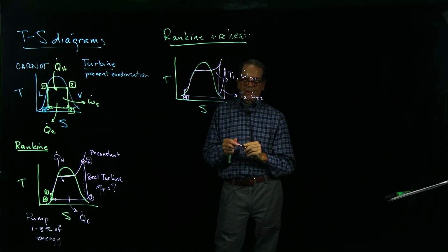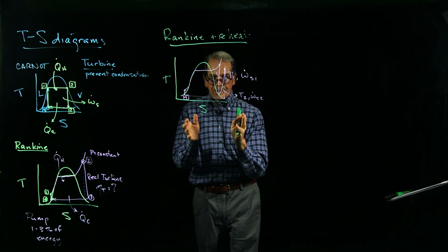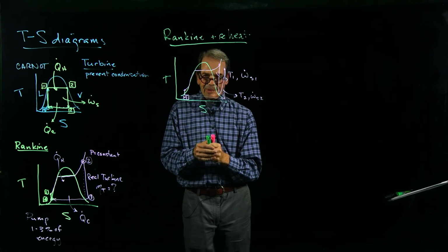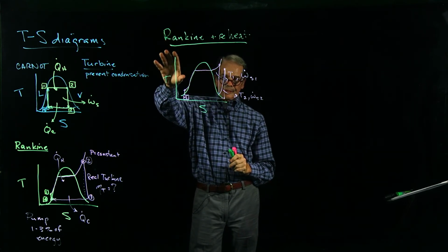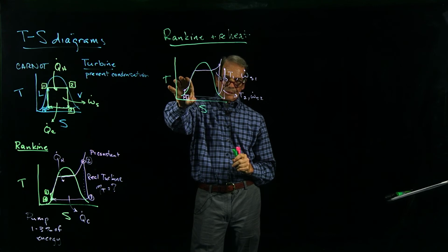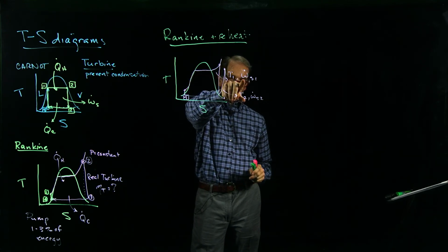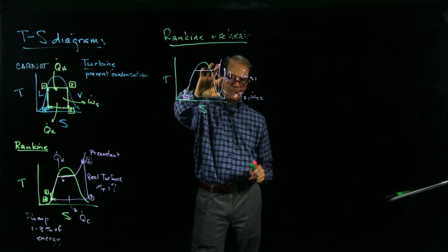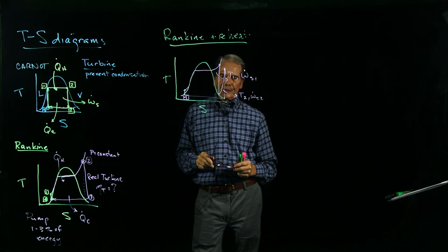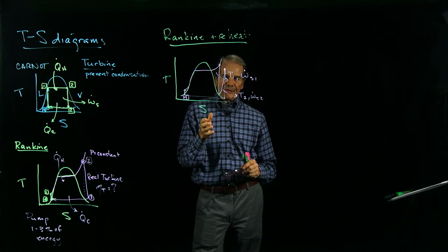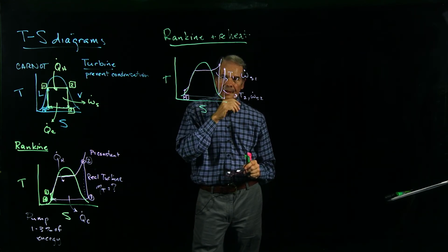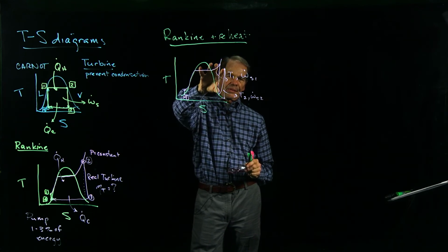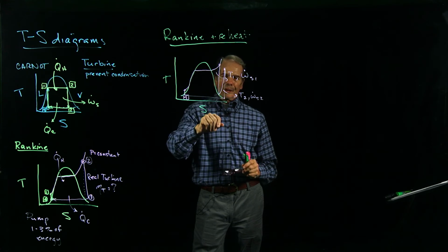Okay, so for example, on a steamship, and particularly a Navy steamship, if we're going to do a Rankine steam cycle, we will use a pump. We'll have 2 turbines, a high pressure turbine and a low pressure turbine. The difference in pressure is probably on the order of a factor of 4. We'll get to the pressures later when we do the actual problem.